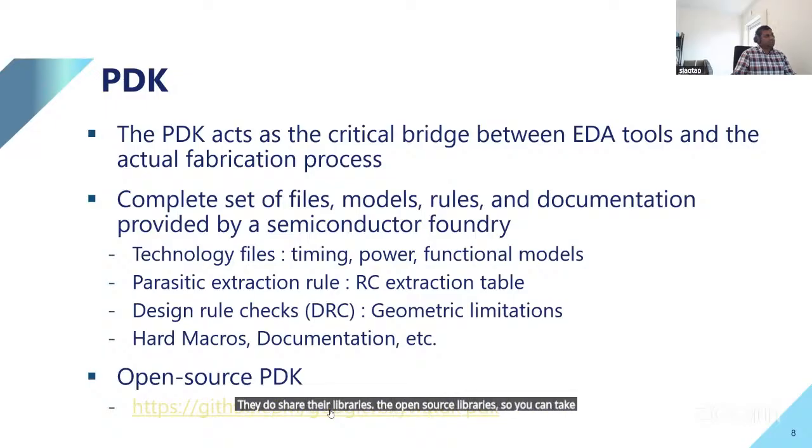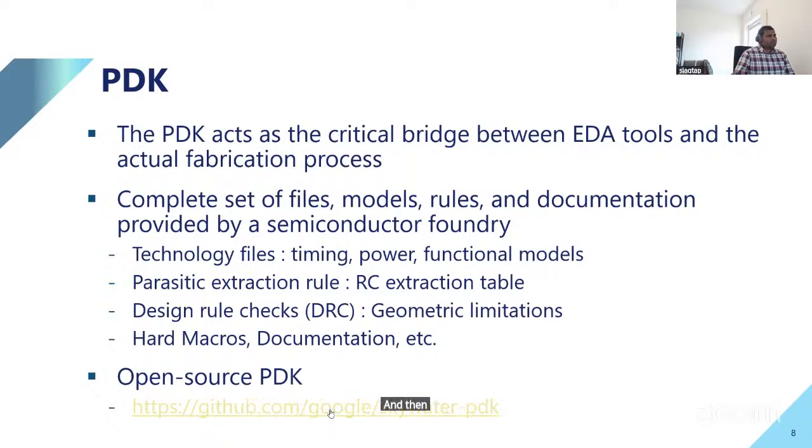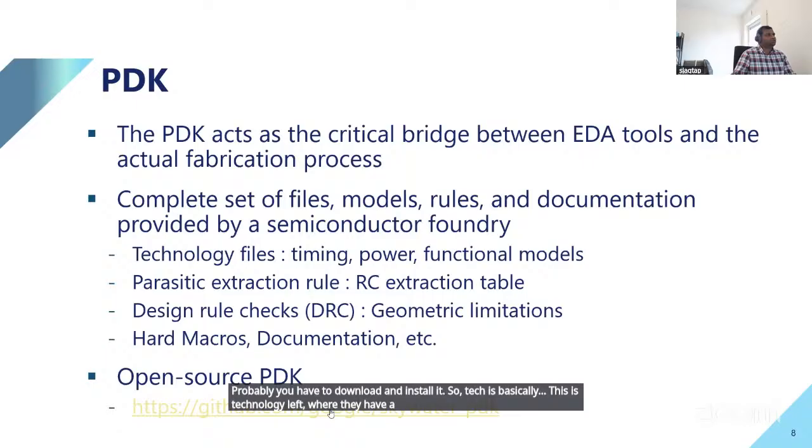I can see this is basically the same library, but in different flavors. I believe LP stands for low power. Probably you have to download and install it. This is the technology LEF, where they have the geometric limitations, and then the timing.